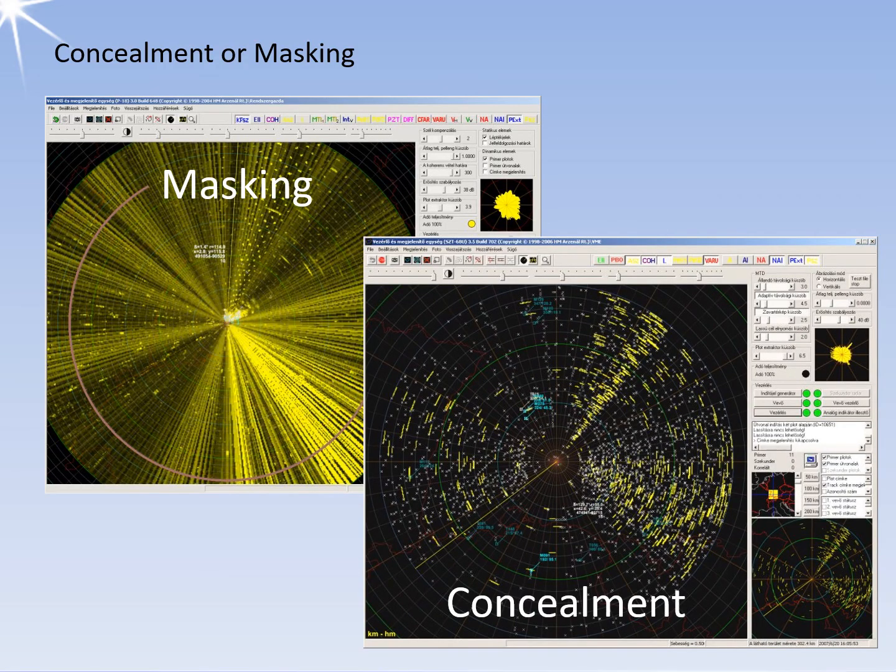The aim of deception is to imitate the radar's probing signal and create a false image of the threat situation. Deception might be better called forgery. During deception, false target signals are generated which the radar receiver accepts and processes as real targets. Deceptive jamming causes a radar to draw incorrect conclusions from its desired signal and the jamming signal, as shown in the lower figure. This kind of pulsed jamming can mislead the radar from the target in range, angle, or velocity. With deceptive jamming, the radar receives a valid return signal and mistakenly believes it is tracking a valid target.